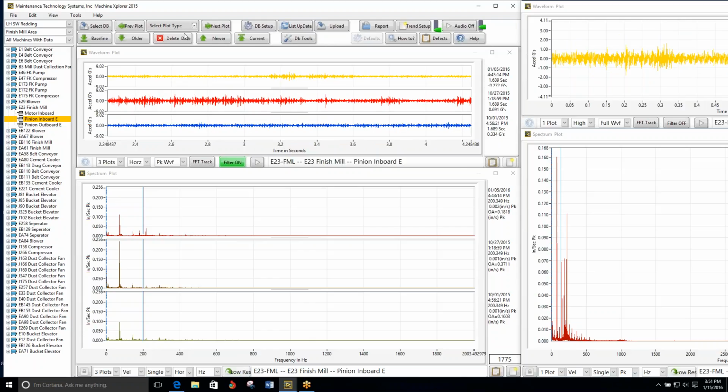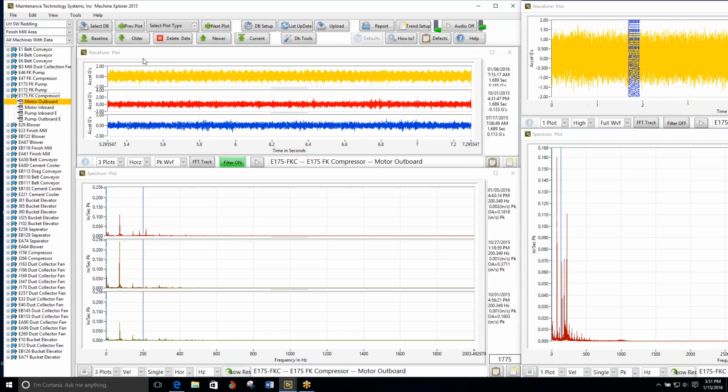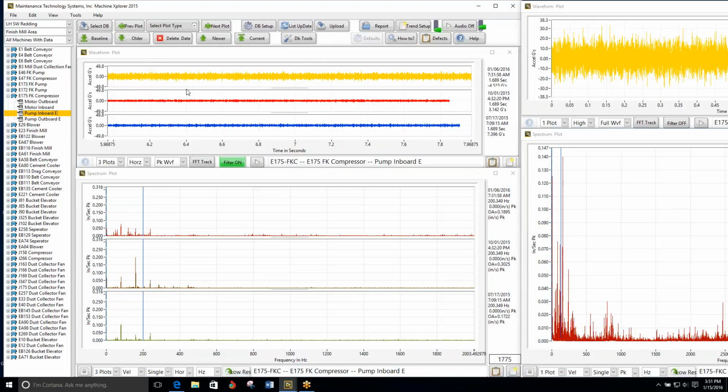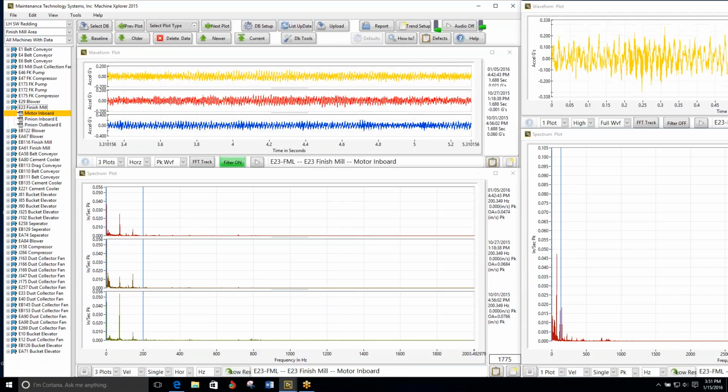Well, this compressor's come pretty close to hitting the upper end of our transducer range, because our transducer range is plus or minus about 55 Gs before it overloads. Do you know what the plus or minus is on that 10 millivolt sensor? Yeah, 500. Yeah. But I measured 660 Gs one time in peak view.